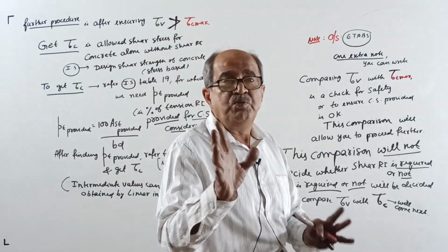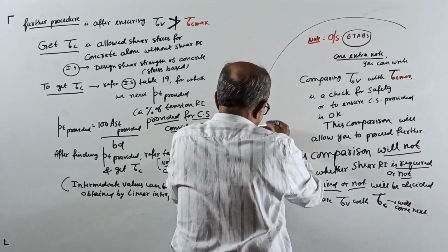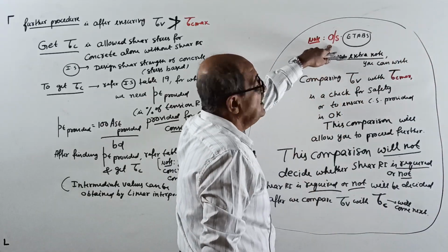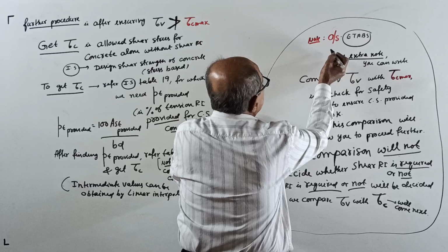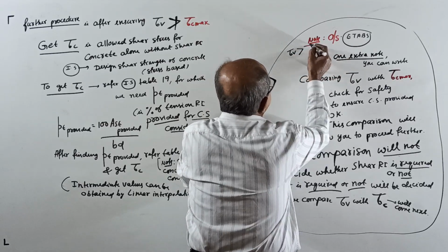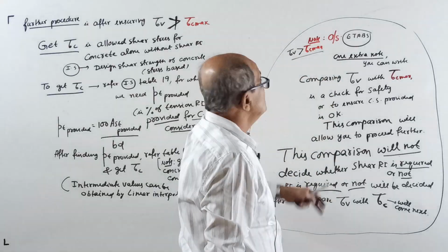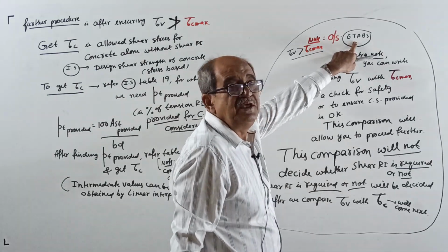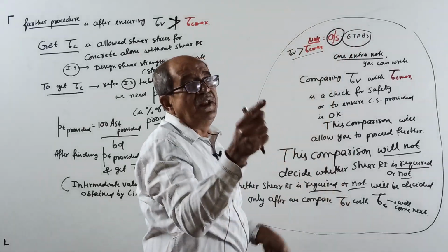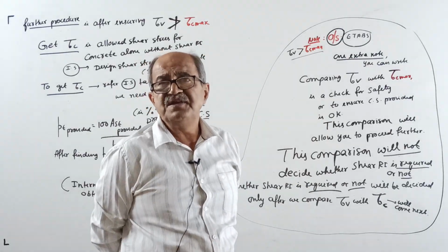Okay. Now, before proceeding further, one extra note you can make. It's only a note, not procedure. In case tau V comes more than tau C maximum, if you do manual design, you have to redesign. In ETAP software, in red color, you can see O by S. So whenever you see O by S in red color in ETAP, it means the cross section is inadequate.